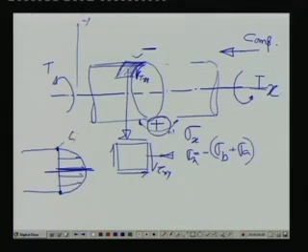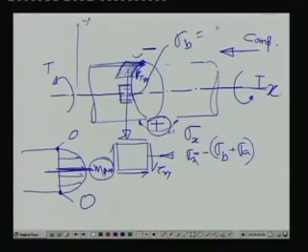It becomes 0, zero stress, and this becomes your maximum at the center point. So, what is the value here? This is direct, this is 0. Now, in the similar manner, if I take over here, then we get the direct stress to be maximum here. But if I take an element at this point, you can see sigma bending must be 0.